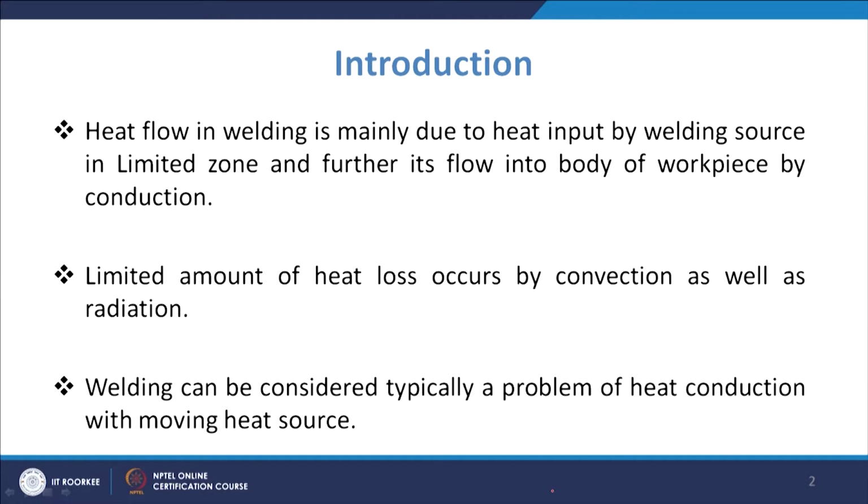And certainly when you have a liquid metal pool which is exposed to the surrounding environment, there will be some loss to the surroundings by radiation, and there will also be some loss or heat flow by convection. But we neglect these, because that is a very small amount compared to the heat flowing into the body by the conduction mechanism.